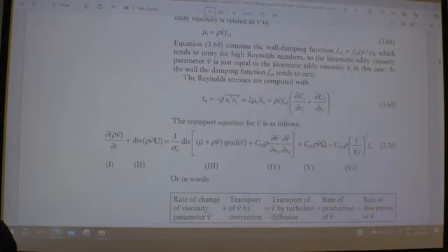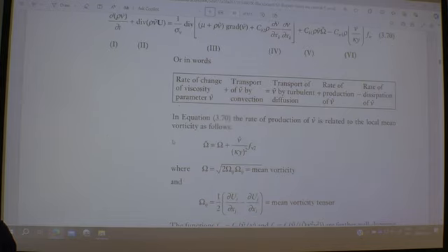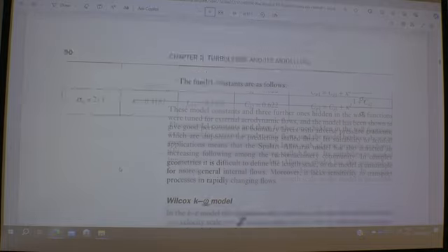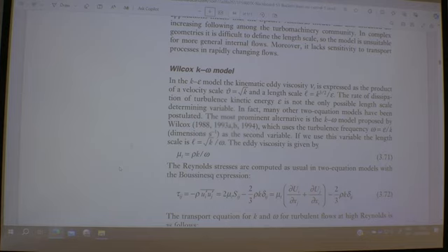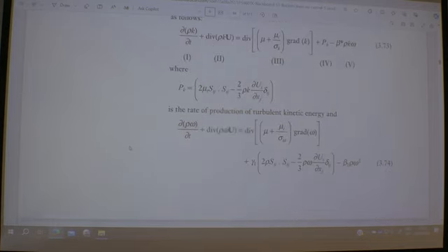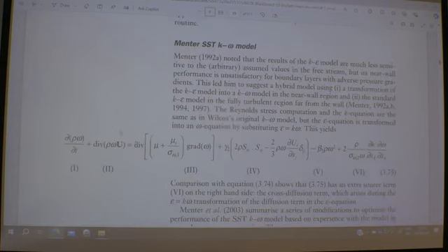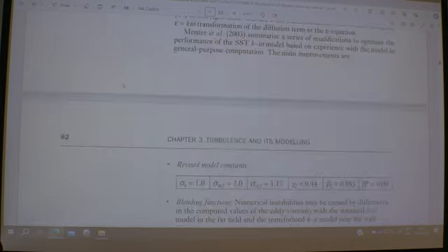Here, the Spalart-Allmaras model. Just one transport equation for the eddy viscosity. A lot of modeling there as well. And then the K-omega. And again, everything is modeled. And here the K-omega SST. This was a mix between K-epsilon and K-omega, trying to use the best of both worlds. So it's sort of a hybrid model. Actually quite a good model.